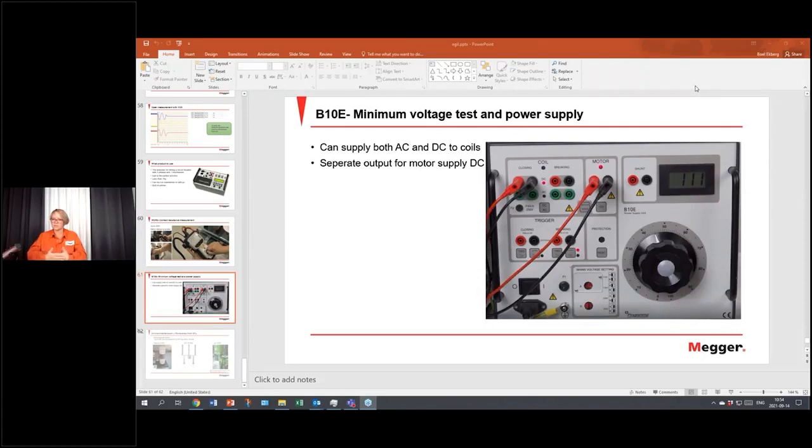It can be dirty surfaces, it can be bad contact pressure, but the most common fault is that people have made a mistake when connecting the current and voltage sensors. They need to be in good contact, because otherwise you're measuring the resistance between the clamps and the object. If you have a painted object, for example, it's really difficult to get a good contact. So you really have to make sure you have a good contact when measuring, because that's actually the most common problem: a mistake made while connecting.